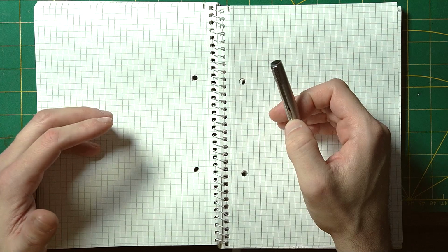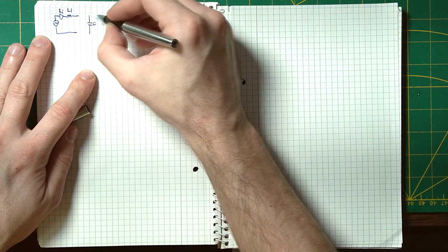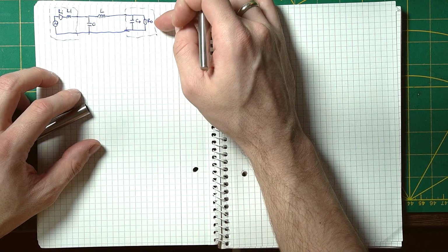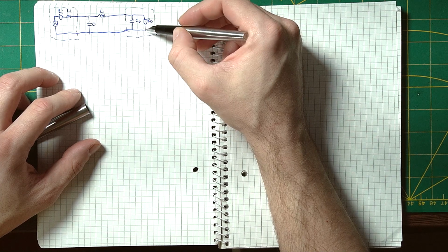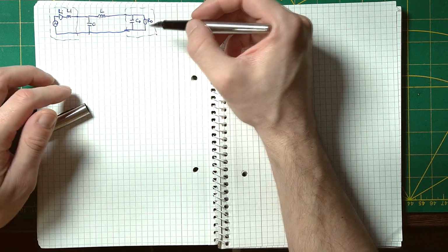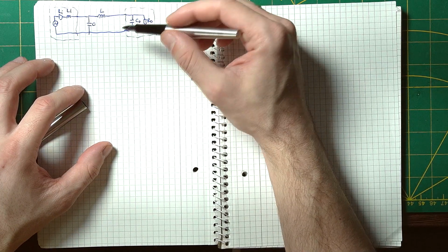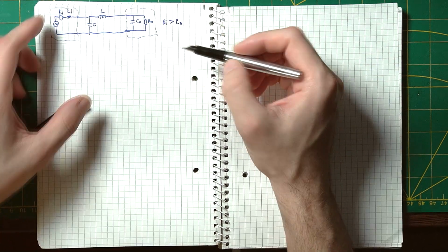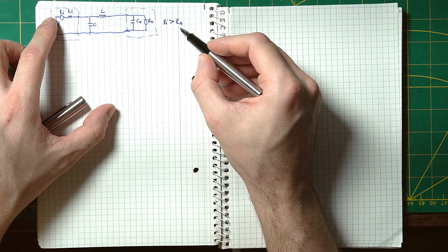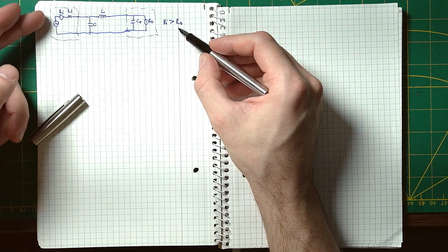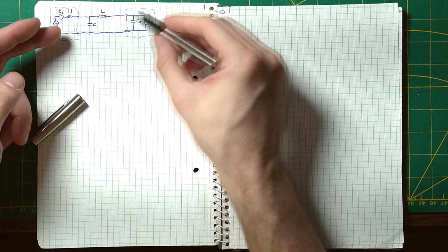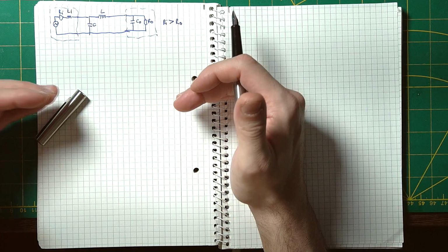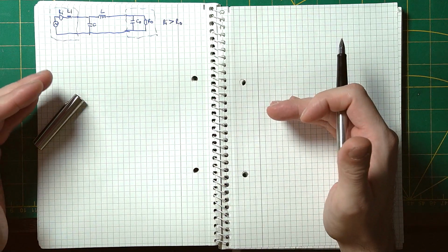So the circuit that we will end up designing looks something like this. We have our signal source with an input resistance and series inductor, and then we have our load with a parallel resistance and a parallel capacitor. And in between them we have a two-element matching network. Capacitor in parallel, inductor in series. Now, since our internal resistance is larger than our output resistance, we have a capacitor in parallel on the larger resistance side and then the inductor in series with the smaller resistance side. So we need to find an equivalent circuit with some intermediate resistance values that will make this thing work.